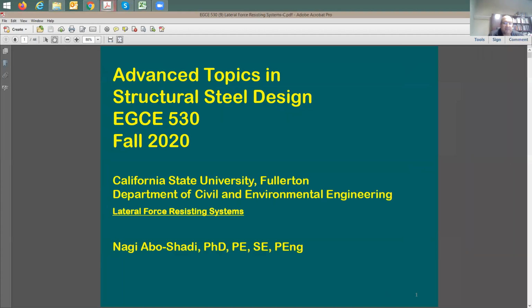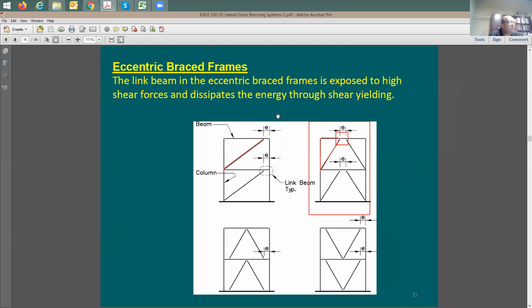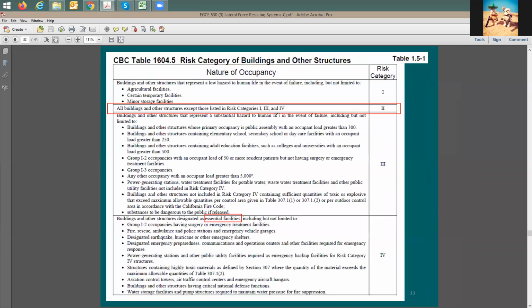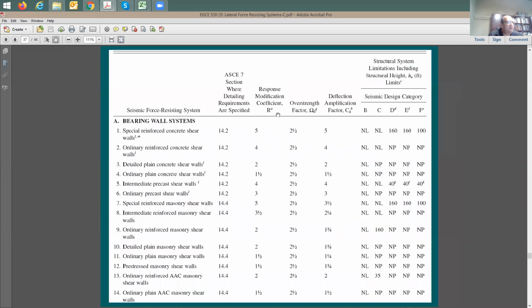Okay, let me open this. The type of building that you're going to be constructing, so for safety. Yeah, and look at this. Here's the importance. Just to remind you, because this is also on your midterm: based on the seismic design category, you can figure out one of the things that is going to be greatly affected by this. Based on the seismic design category and the structure system, we can figure out the height of the building. So the selection of the structure system is really going to be based on the seismic design category.